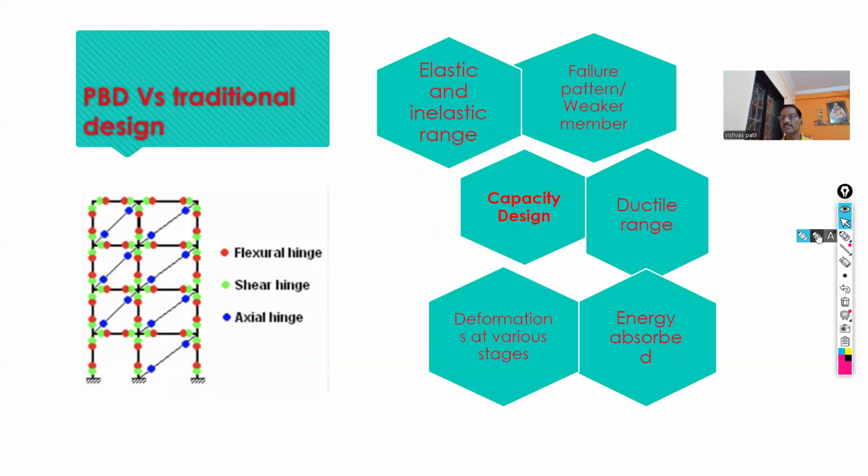Thus, by using performance-based design, we can calculate elastic as well as inelastic behavior of the structure. Then we can learn the failure pattern, which are the weaker elements which fail first, and what is the sequence of the failure. We can also observe the ductile range of the structure.